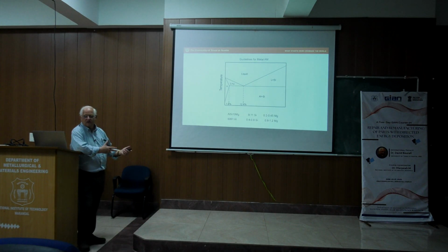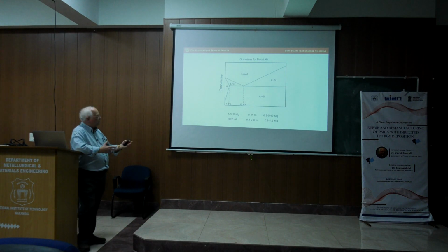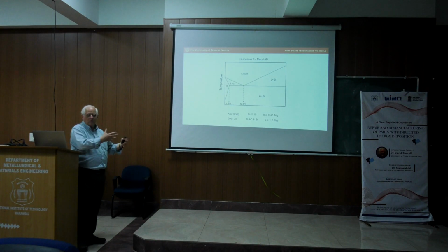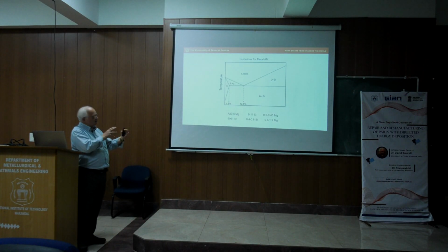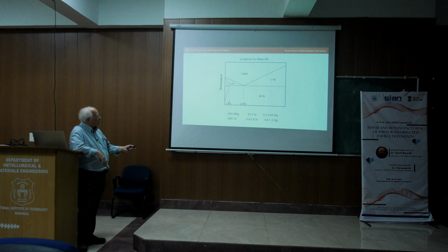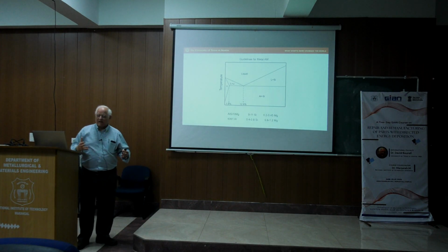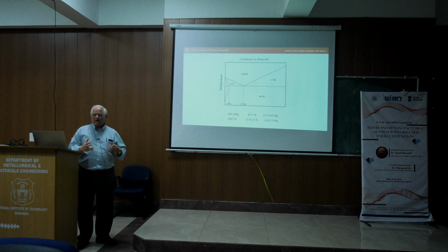It turns out it's actually a so-called eutectic composition. We don't see it on the binary diagram because when we add the magnesium, it shifts the diagram a little bit. But basically, for this system, if we plotted aluminum magnesium with this amount versus silicon, what we would see is that this 9 to 11% silicon would be right at the eutectic here. What happens with this is sort of universally true of casting alloys.